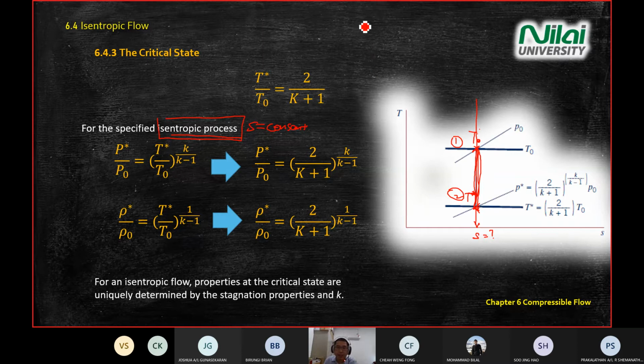If you learned about thermodynamics before this, you know that if you draw T versus S, the pressure lines will always go like that: P1, P2, maybe this one P3. Always at a diagonal angle. So you just go through the intersection points. You draw this line as a pressure line, this one as a pressure line, and again this one passes through a critical point, which is a star. So this one becomes star, and you can draw the line on the TS diagram.